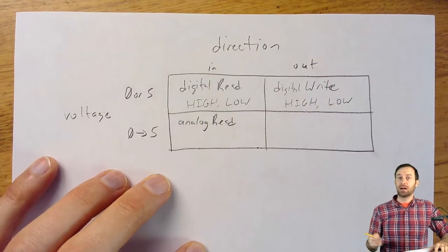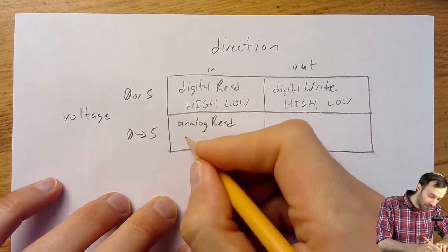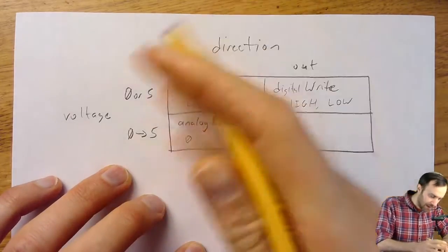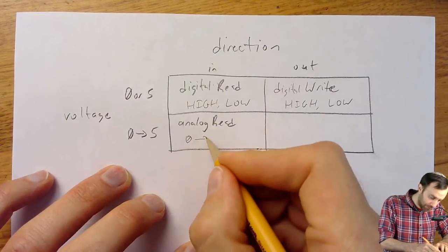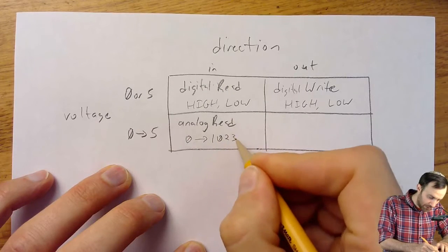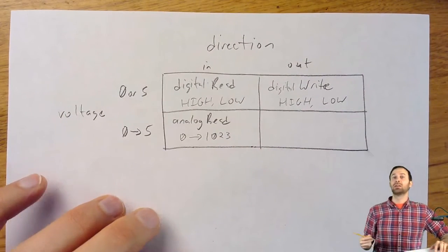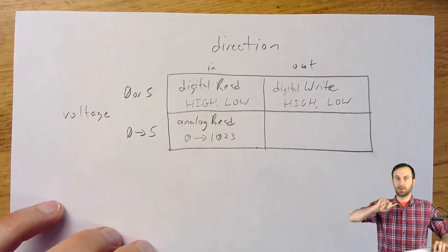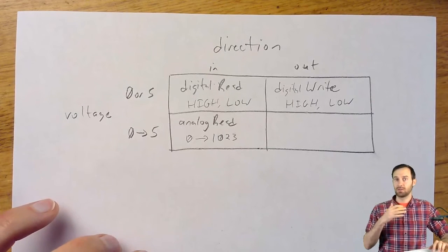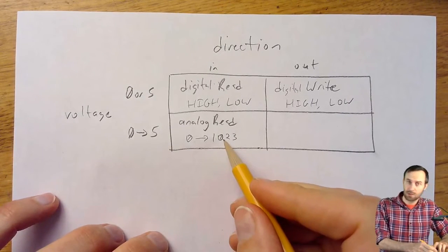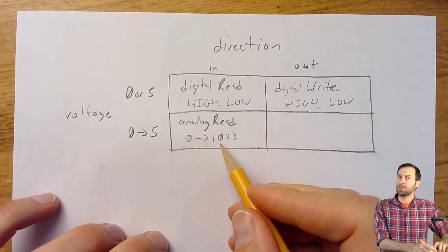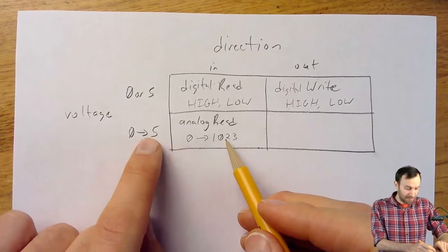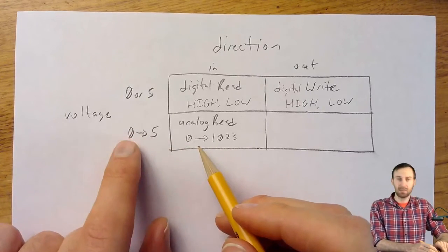And the possible values for analogRead: the lowest value of analogRead was the number 0, and the highest possible value of analogRead was 1023. You would have seen that observationally if you had done the simple sketch where we first plug in the potentiometer and then start turning it back and forth and just looking at the values coming into the Arduino. You'll see the highest one is 1023. That does not mean 1023 volts, though. That actually means 5 volts. That number maps to that, and the number 0 in analogRead means 0 volts.